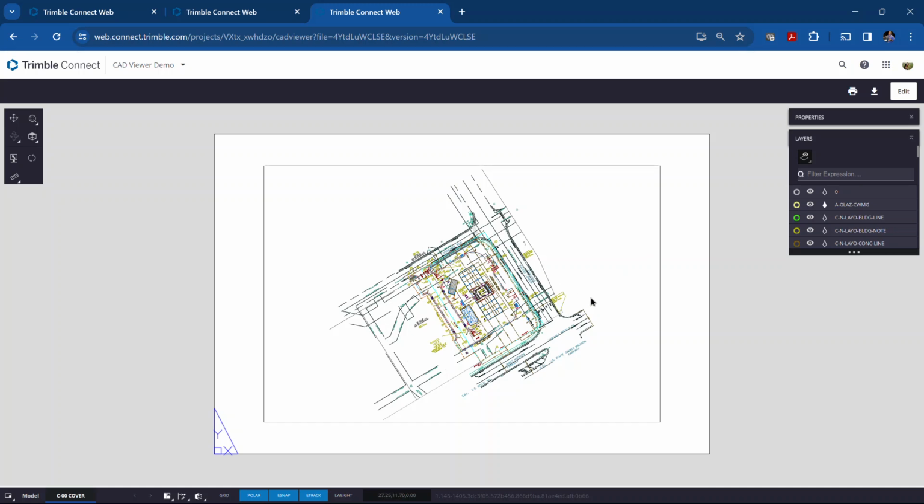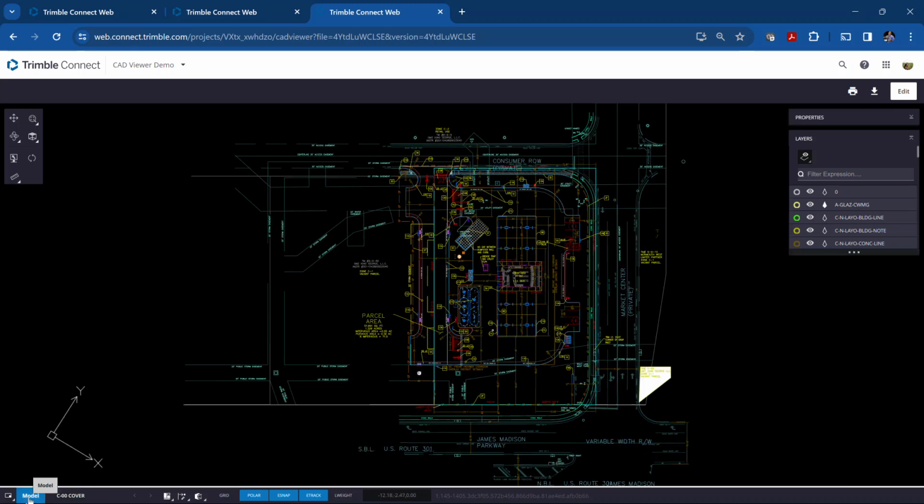And within that paper space, I have this viewport that lets me scale the drawing. So when I plot it, it's at a certain scale, like 1 to 40 feet or 1 to 50 feet. So basically 1 inch equals 50 feet. And that way you can properly scale objects if you print this off on a plotter or printer. But primarily you're going to work inside a model space.